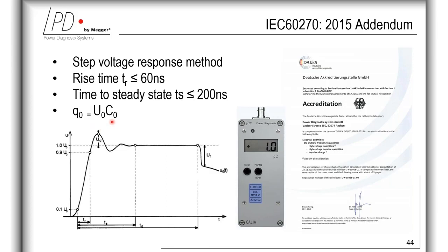Very importantly, it has an injection capacitance which is lower than 1 picofarad, in the range of 0.8 picofarad, and this value stays constant with every charge value. The general principle of the K1A is keeping the injection capacitance low and fixed with every charge value and increasing the step voltage with the injected charge value, like in this formula.